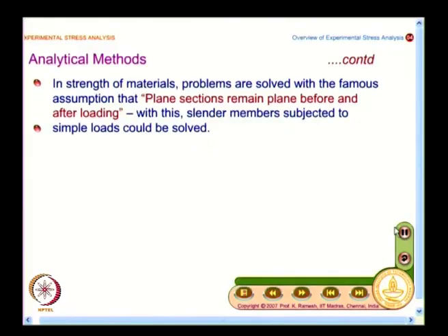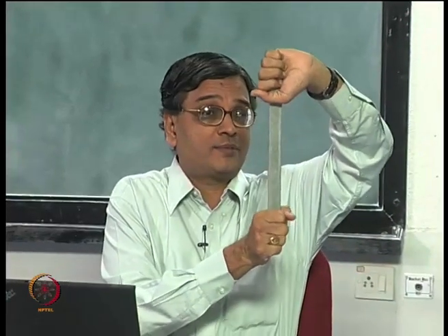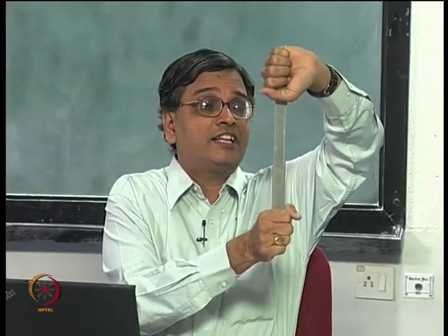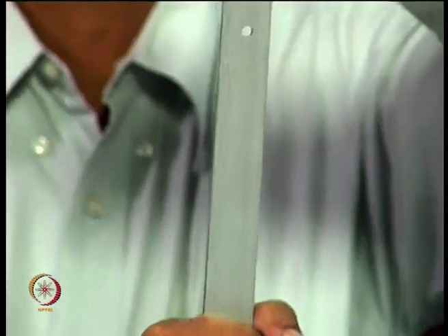And what you find here is, one of the basic assumptions is plane sections remain plane before and after loading, and with this we have solved a large number of problems which are slender in nature. It is very important. Suppose I take a plate and then stretch it like this, I have no problem. Suppose I put a hole there, I cannot do it with strength of materials.